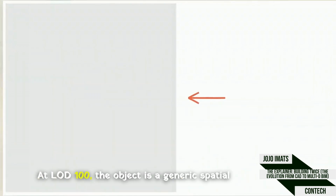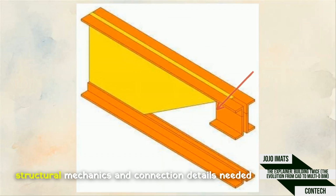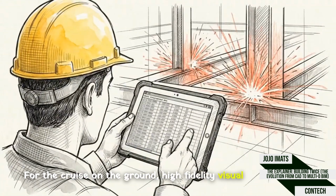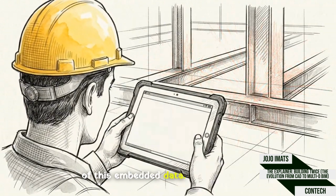We measure the reliability of this data using the Level of Development, or LOD, specification. At LOD 100, the object is a generic spatial placeholder. Compare that to LOD 400. At this stage, the model contains the precise structural mechanics and connection details needed for fabrication. For the crews on the ground, high-fidelity visual detail is secondary to the absolute reliability of this embedded data.